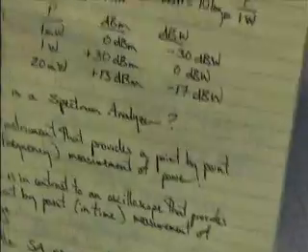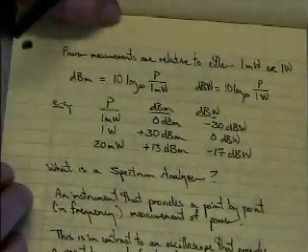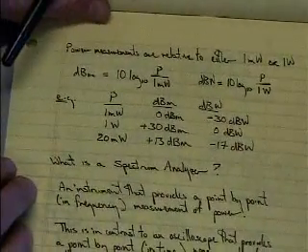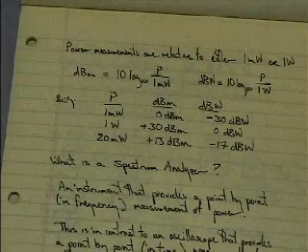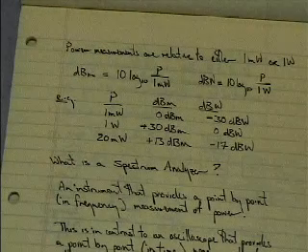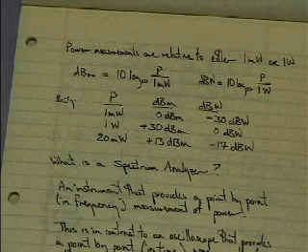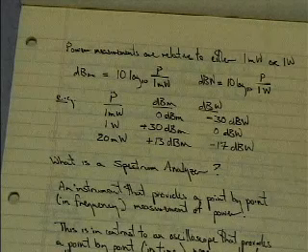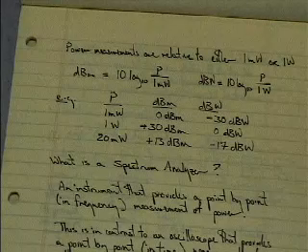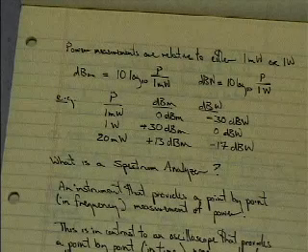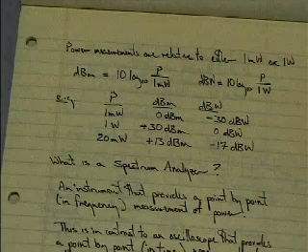What about power? If we noticed in the ratios or in gain, our units were dB. When we're doing power, we want to have watts floating around somewhere. So what we do is take the ratio of whatever power we're considering relative to either 1 milliwatt or 1 watt.